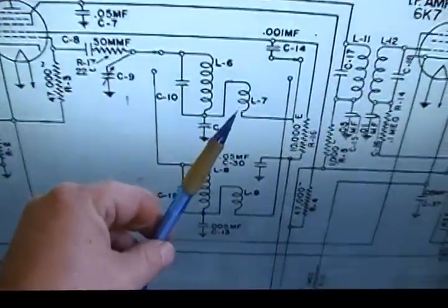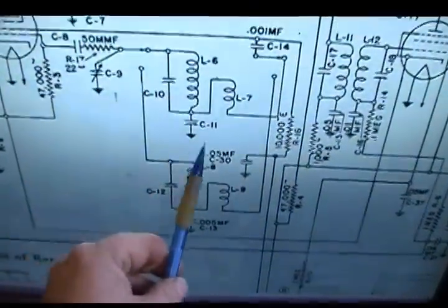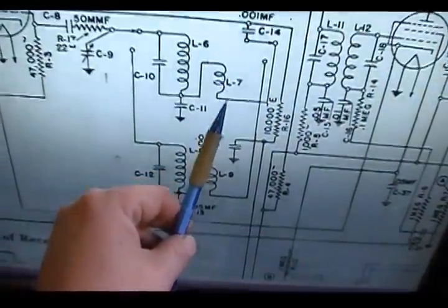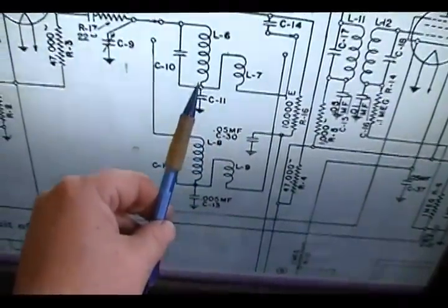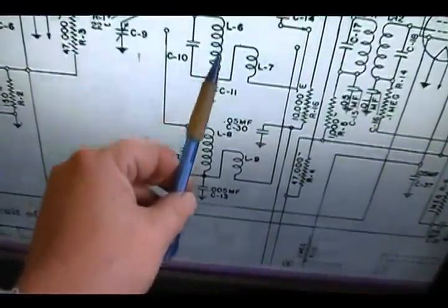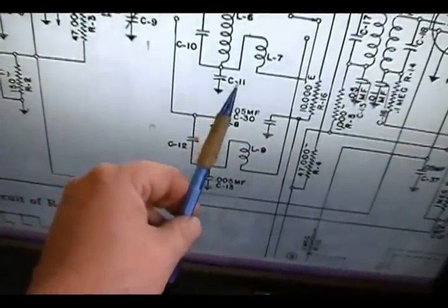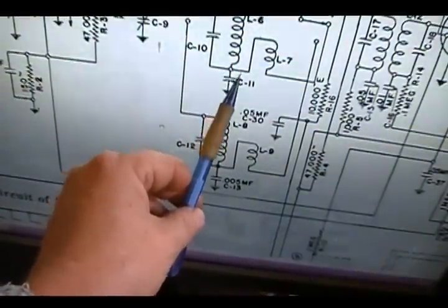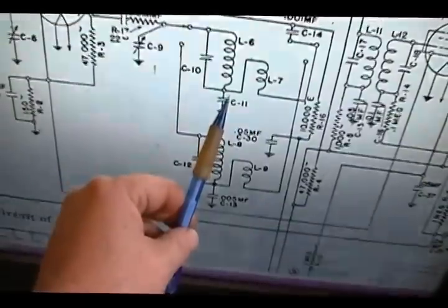So you see here, this is the broadcast oscillator coil. One end here of the Tickler coil, fewer windings, goes here, the other end connects here. They go through a tuning cap and go to ground. But the main thing is they've got a connection right here.